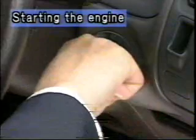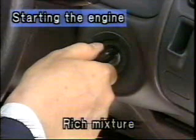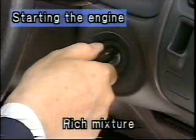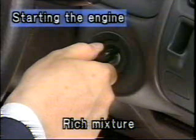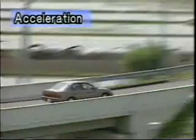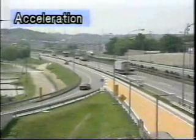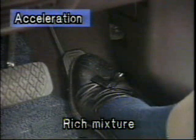Now let's look at different driving conditions, beginning from when the vehicle is started. Naturally, the engine is cold, making it harder for the fuel to be atomized. This alone is enough to create an improper air-fuel mixture. Hence, it is necessary to provide a greater ratio of fuel to air. Next, when the vehicle is accelerating. We know that fuel is heavier than air, so since the amount of air is increased when the accelerator pedal is pressed, the amount of fuel also must be increased to obtain sudden acceleration.